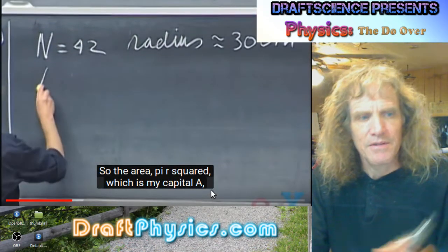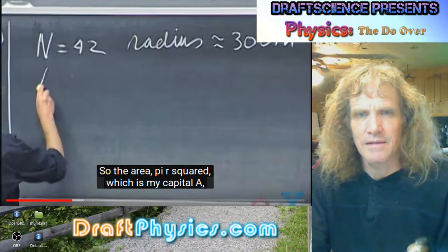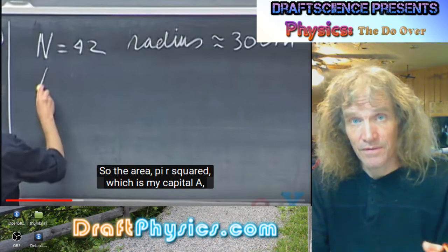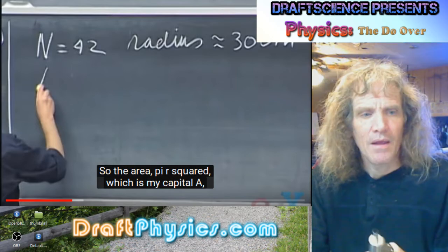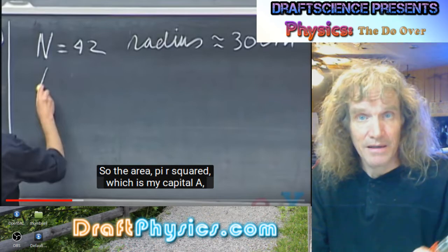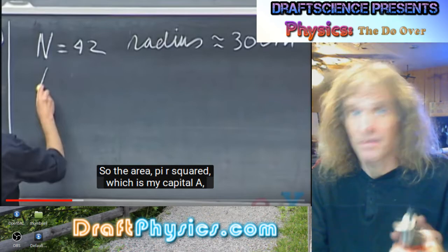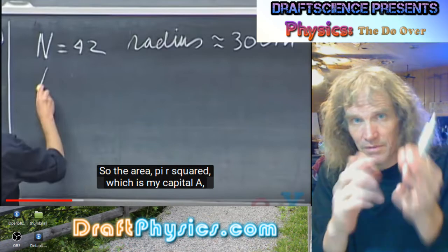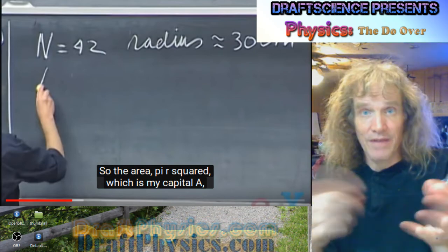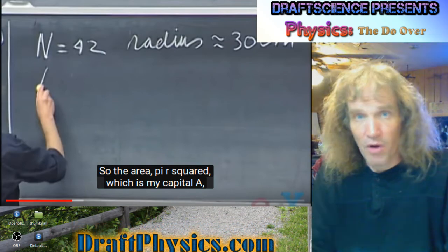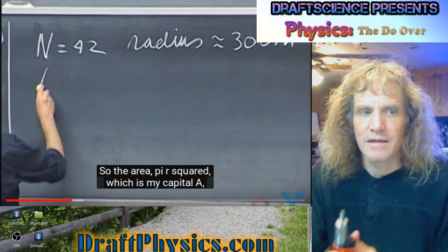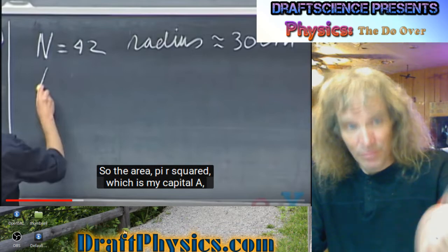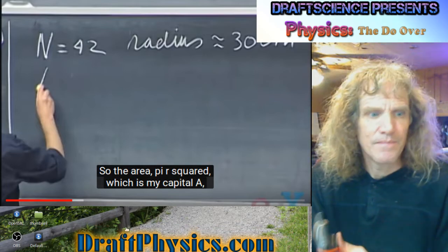Right. So area becomes kind of important here because you're recognizing that this is a rather large loop. So there's a lot of surface to be collecting. And he's going to just be using the Earth's magnetic field. So he's using a very weak magnet, but a lot of wire, in a sense, proportionally. If you made it small and converted that same area into this small thing, you'd end up with a lot of windings. I just think you have to think that the reason why this works is because it is a rather large loop.